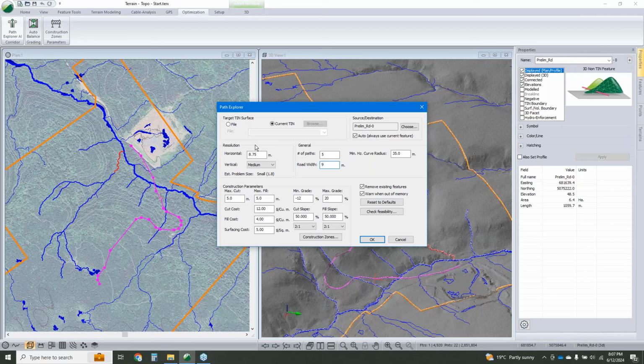We're going to keep it 9 meters wide with our simplified cross section. I'm going to let it be steep, but not super steep, so we're going to max it out at 18%. And I want 5 options. It's going to give me however many options I tell it to, within I think a ceiling of 10. So it will adhere to those design constraints.